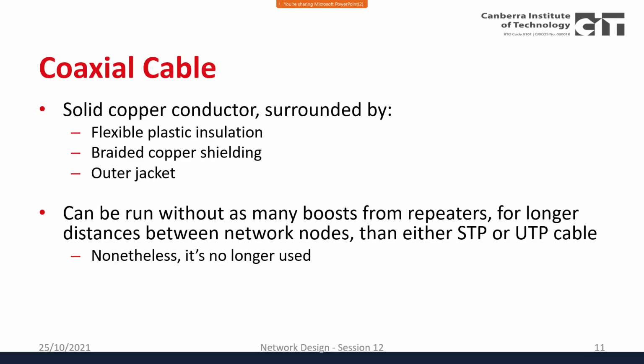Question, Robert Yakovic? How far away would you recommend to put the twisted pair cables from the electricity cables? So the twisted pairs, Kavish, there's actually a regulation that tells you exactly how many meters. Now, from the top of my head, I don't remember, but with my experience, I would recommend at least probably 2-3 meters. I know it may not be possible sometimes, but yeah, I would recommend at least 2-3 meters away, just in case.